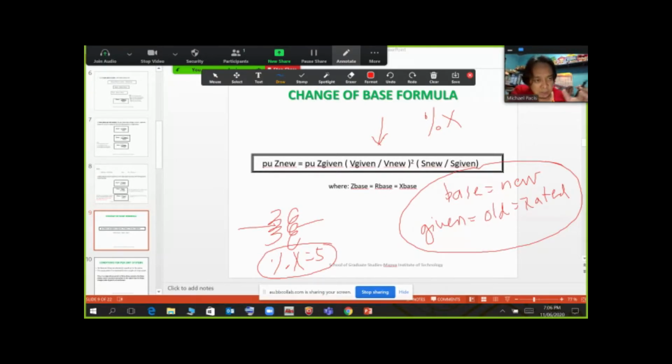So what's the moral lesson of the story here? You will use this formula if you see percentage values along the power system or along the rotating machines or equipment, transformers, and motors. Those are typical equipment where you can see percentage reactances. Sometimes not percentage reactance, but percentage impedances, which are composed of R and X, or real and imaginary parts, respectively.